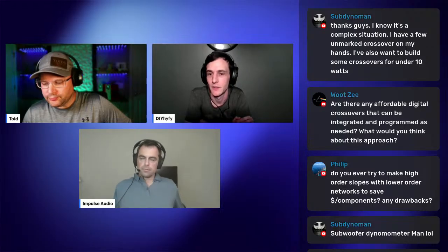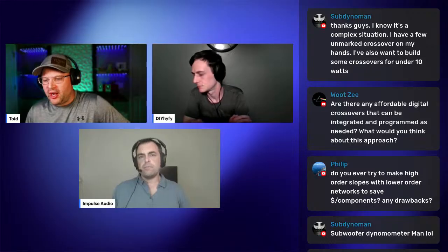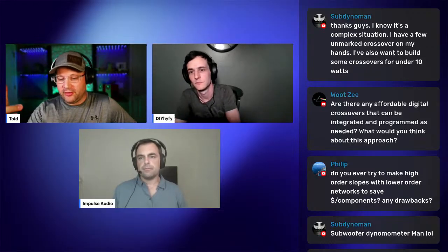Yeah, especially if you're crossing woofers over lower, it's quite likely you're going to have to go to higher orders to get the roll off that you're looking for. And that's what we should talk about. So there are differences between first, second, third, and fourth order crossover points. Some of it has to do with phasing. Some of it has to do with how steep the slope is.